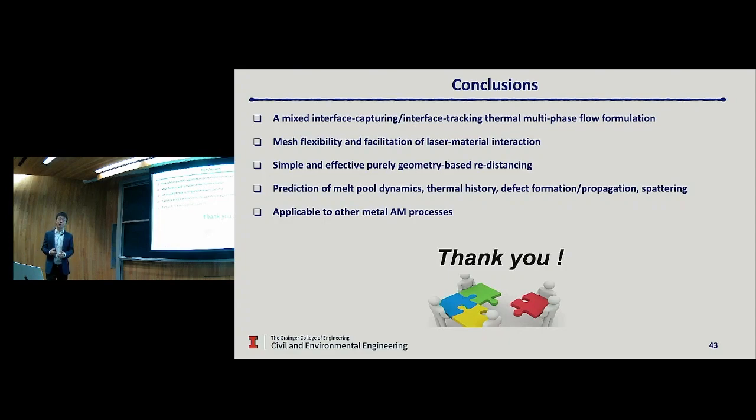But the scanning speed and the laser power have been experimentally investigated by Argonne National Lab. There are some findings there. For example, like I mentioned, faster scanning speed leads to smaller depth fluctuation. That's true. And the scanning speed also affects pore formation. There is a threshold combination of laser power and scanning speed. It's a boundary: on one side you will have pores, and on the other side you don't have pores. Yeah. Thank you. Thanks.